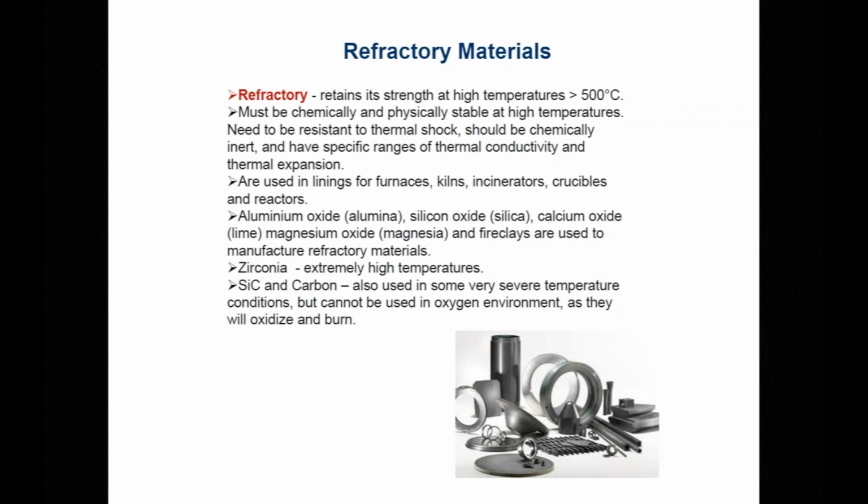So for refractory materials, they can be produced in high volume, large furnaces such as you find in the steel industry, or small cabinets where you can basically graphitize, digest, or heat up and remove any organic components. So basically, beyond 500 degrees C, 750 degrees C, most organics are gone. Metals start melting. But once you go to 1,000, 1,500, 1,800 degrees C, you'll only be left with ceramic or refractory materials.